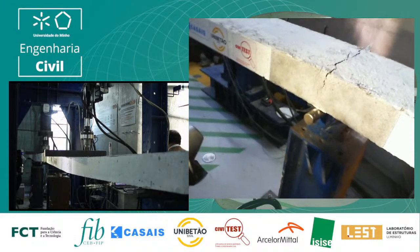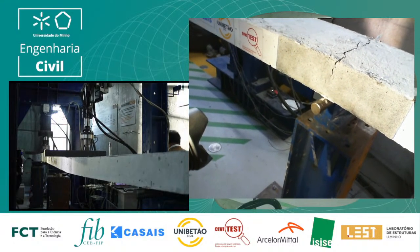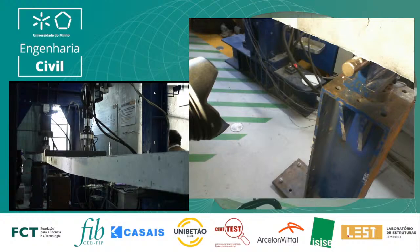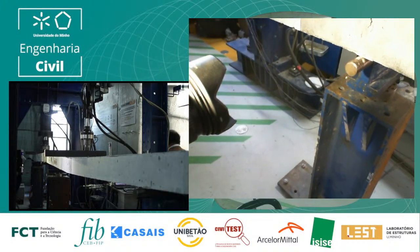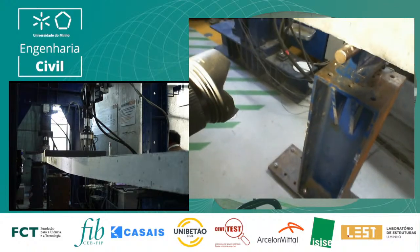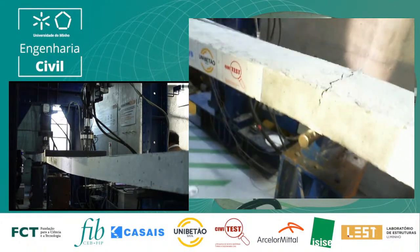Now, in reality, the continuous beam is working like two simply supported beams with a resisting bending moment in the support region equal to the plastic resisting bending moment. Okay, so obviously plastic, but considering the contribution of the fibers.